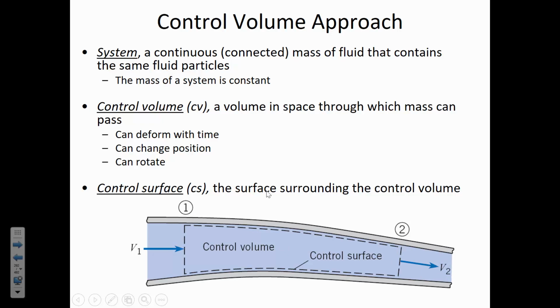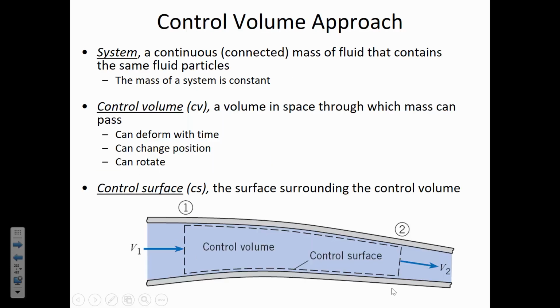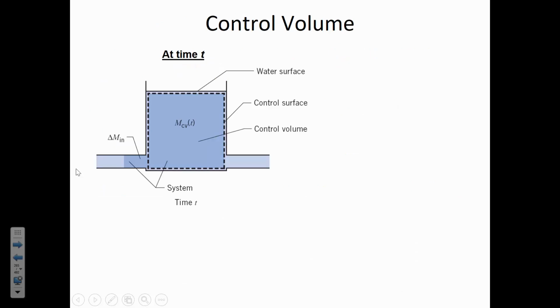So the control volume approach is really just like, you can think of it as accounting. It's looking at in and out and where it is over time. And so let's look at a little bit more complicated example, like what if we had some capacity for storage? In the first illustration here, it's just a pipe that's already full, so there can't be any accumulation inside of the control volume. But if we instead define our control volume as being this tank that's connected to an inflow pipe and an outflow pipe, now things are a little bit different because there can be accumulation inside of the control volume here. The tank water level can get deeper.